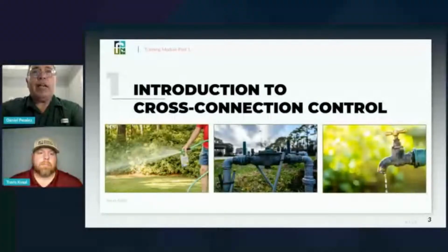We define backflow as an undesirable reverse of flow in the water system from its normal distribution. Once water enters the service line into a facility's piping, it must become a one-way street and flow from the utility's distribution into the home or building and throughout its private water system. Water seeks the path of least resistance. High pressure goes into low pressure.